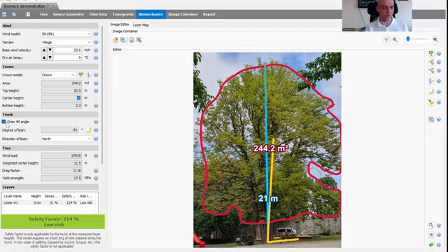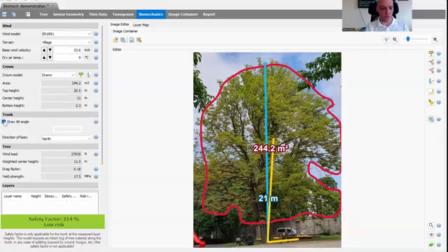So now draw tilt angle means that the tilt angle is used from the drawing itself. However, you can redefine this. Imagine the case when the tree tilts towards the camera or tilts away from the camera. In those cases, you might need to redefine the tilt angle. And the way to do it is unchecking the draw tilt angle and changing this value.